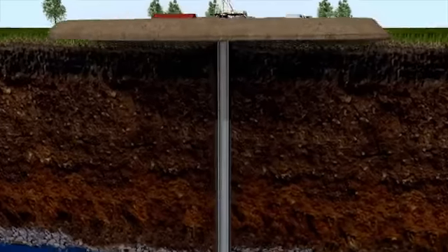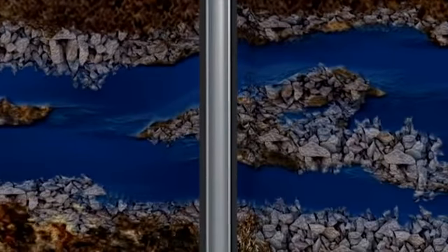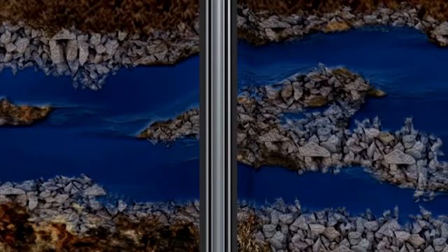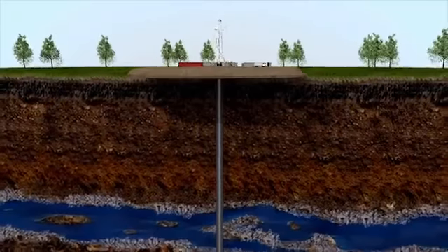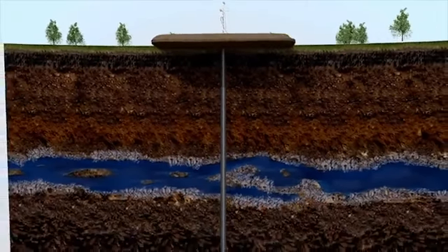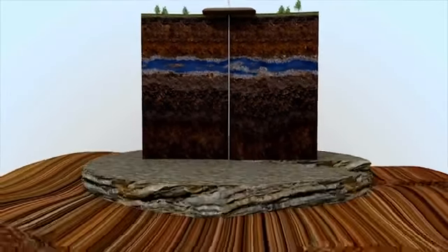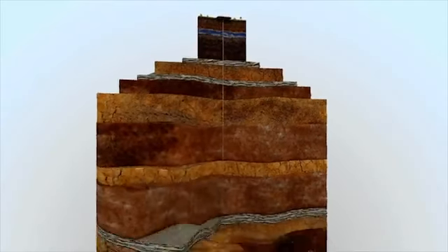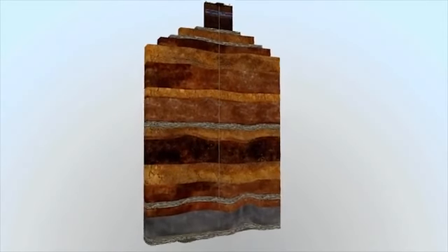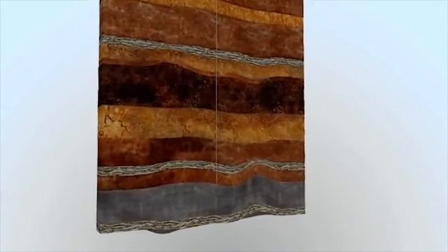In some cases, depending on the geology of the area and the depth of the well, additional casing sections may be run and, like surface casing, are then cemented in place to ensure no movement of fluids or gas between those layers and the groundwater sources. What makes drilling for hydrocarbons in a shale formation unique is the necessity to drill horizontally. Vertical drilling continues to a depth called the kickoff point. This is where the wellbore begins curving to become horizontal.